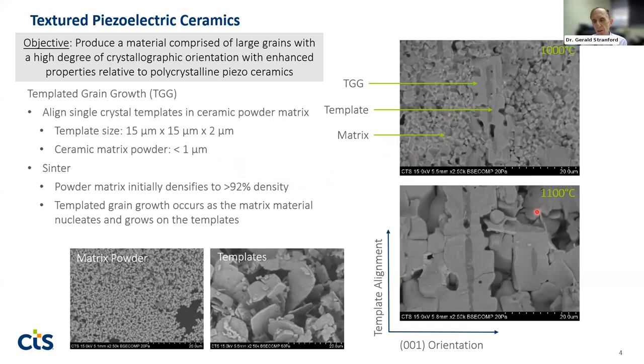We do go to higher temperatures and longer times during our sintering cycle. But you can see you've got a large amount of grain growth around the templates, and the fine grain microstructure is basically consumed, growing larger grains. There are a few areas I want to point out here, because it'll be a topic further on.